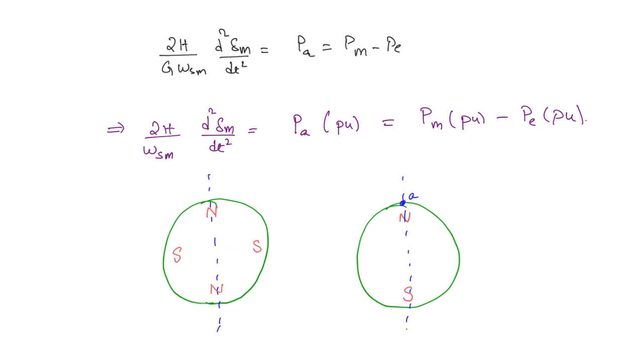But now you see, if you see this 4-pole machine, what is going to happen here? Here north to south is 1/2 rotation in electrical terms, and from again south to north, it is a complete revolution. So here 360 degrees is getting completed in electrical terms, whereas in mechanical terms only half a rotation is being completed, right? So if you take the angular displacement in electrical terms as theta e, then it is equal to 2 times the angle in mechanical terms, right? So when theta m is 180 degrees, theta e is becoming 360 degrees.